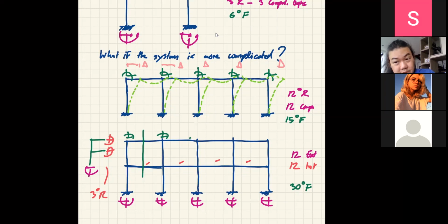But they move if I push them. So that means in the end, our degrees of freedom should come down to how many? 6 degrees of freedom, if axial deformation is neglected. Okay, it's down to 6: 5 rotations and 1 horizontal displacement for this level. You need to have 1.